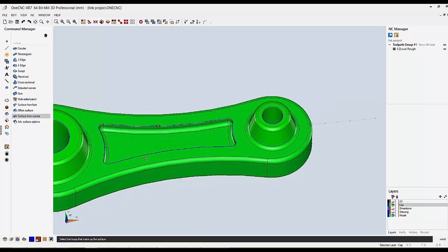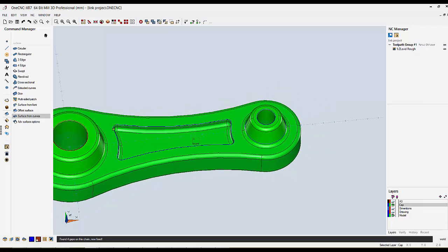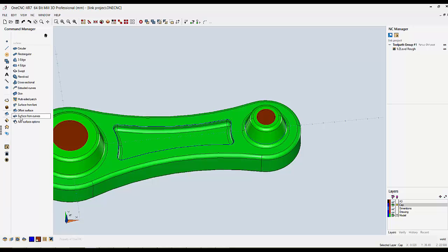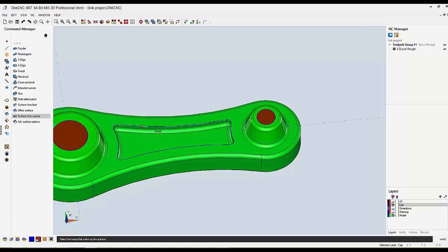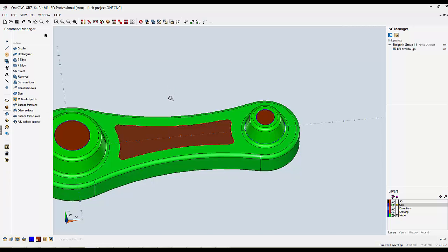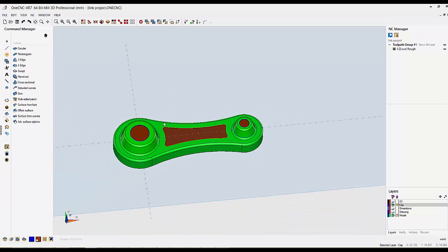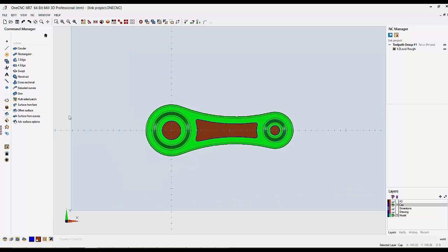We'll digitize the top areas first of all, as they're on the same level. And we'll do exactly the same on the pocket area. So very quickly, I've created 3 blanking surfaces, caps if you like, just to control the toolpath to ensure it doesn't go into that particular area. So let's put a quick toolpath around there so I can show you another big advantage with Mill Professional.